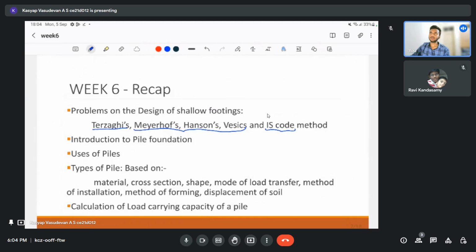What happens is, we bore a hole and install a pile, generally made of concrete. There are other materials also, and it reaches the competent layer such that the resistance offered by this long member, cylindrical or depending on its shape, is enough to resist our load.